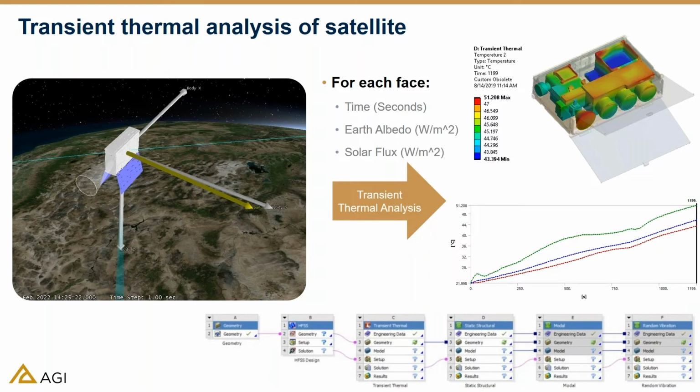Then, considering the thermal strain calculated by the thermal solver, we can perform structural analysis, modal analysis for natural frequency, and random vibration analysis, and so on.